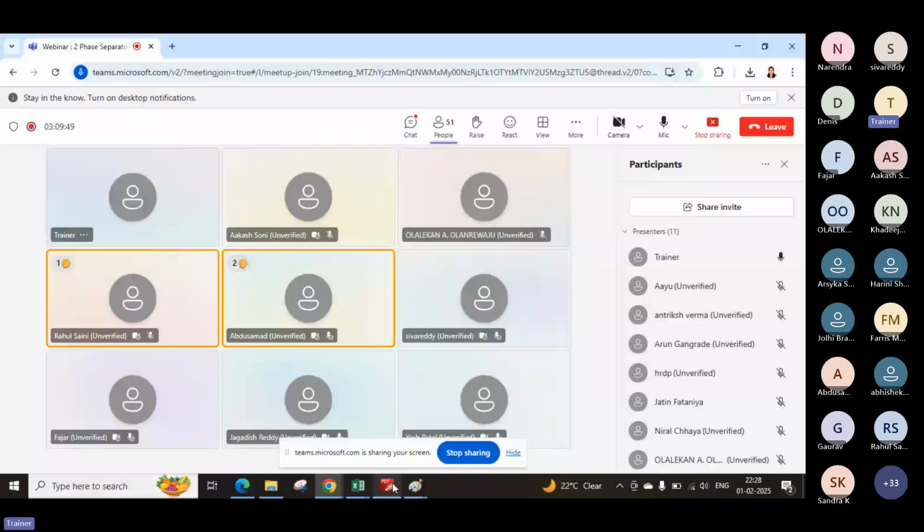Suppose your PSV outlet is 2 inch, then it is connected to 8 inch, then to 16 inch, and then it goes to atmosphere. Then you have to calculate the equivalent length for all these diameters into one diameter. You know the flow rate of the PSV, or you have to iterate the flow, and you know the destination pressure, that is atmospheric. Then you calculate P1 for that flow rate and the equivalent length you have calculated. So you will know P1. That would be your back pressure.